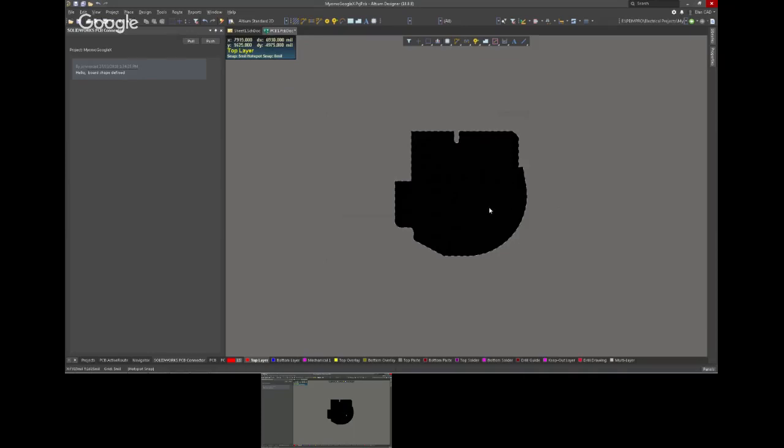Parts placement, right? We said, and Robert said, okay, holes for heat sink, we own it. If it's other mounting holes, they own it. Again, can I place a hole? Absolutely. You can place your mounting holes here and collaborate on this. I'm going to start first with parts placement, and then I'm going to come back to holes and placement barrier.